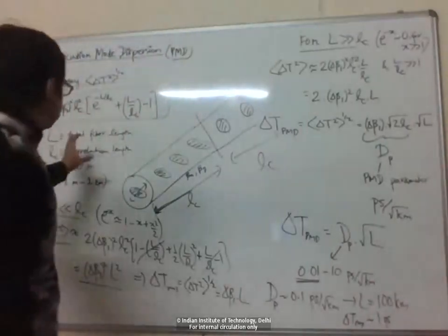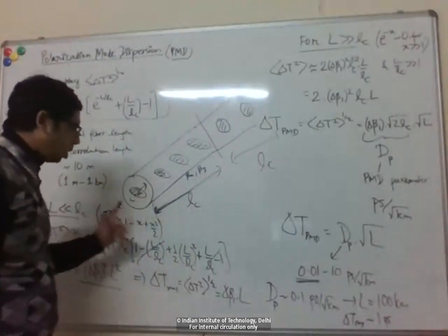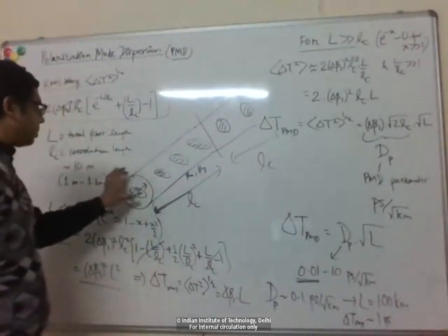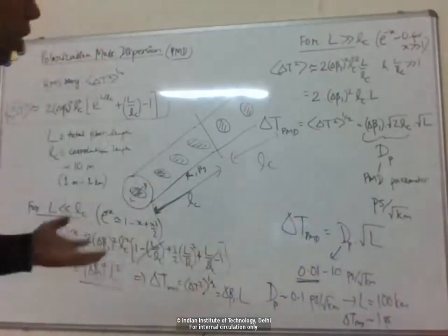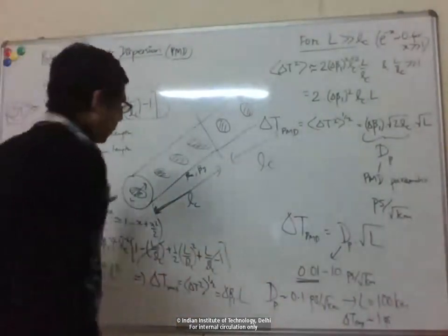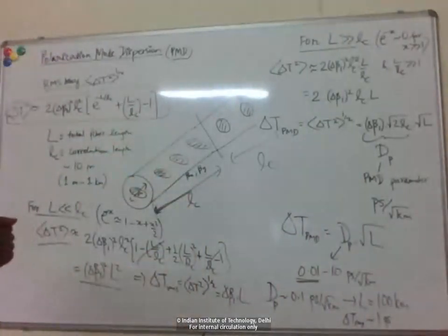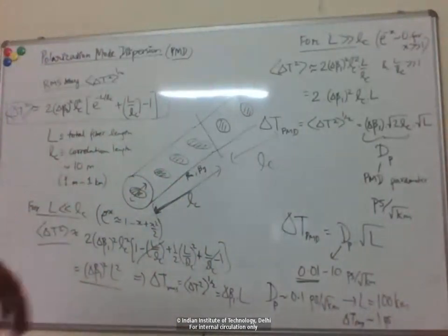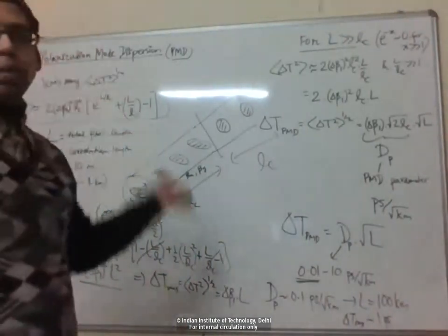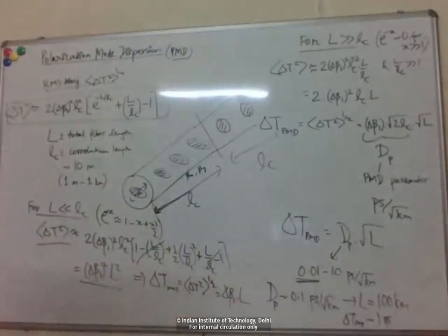This discussion is only for one mode and the two orthogonal polarizations: single mode fiber, only the LP01 mode, and then the two orthogonal polarizations. If you have higher order modes also, then each mode will have its own PMD. But we don't worry about PMD for multimode fibers, because the intermodal dispersion is much bigger, as we discussed first. That dominates over everything.